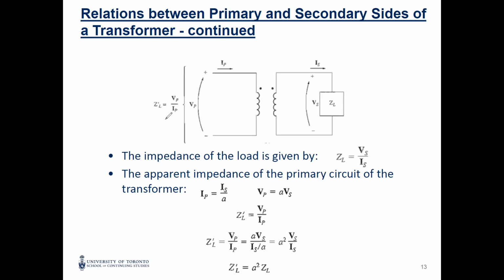Yeah, this is a very good question, because we will see now in the tests, the open circuit test and the short circuit test, we are going to change the transformer from one side to the other side. For example, the open circuit test we will do on one side, and the short circuit test we are going to do on the other side. So we have to know how to move from one to another. In the exam, sometimes they change. They will give you some numbers and then they will ask you, okay, do it on a certain side.